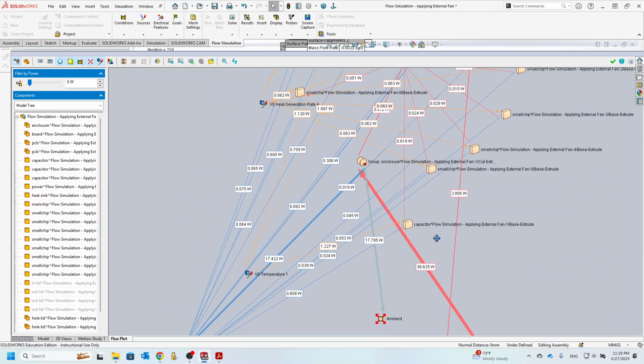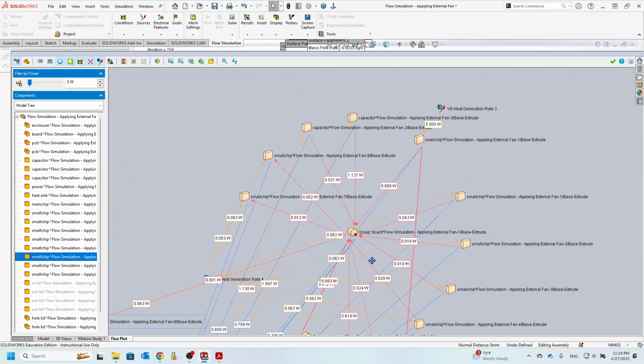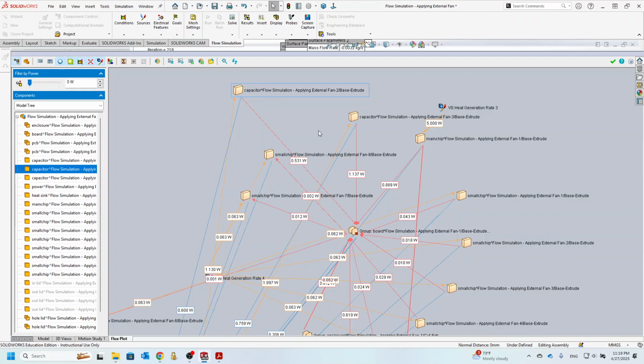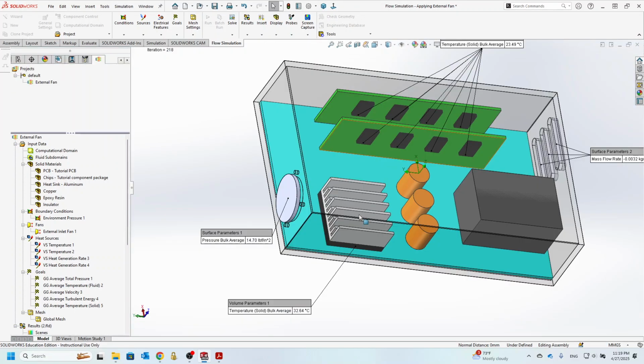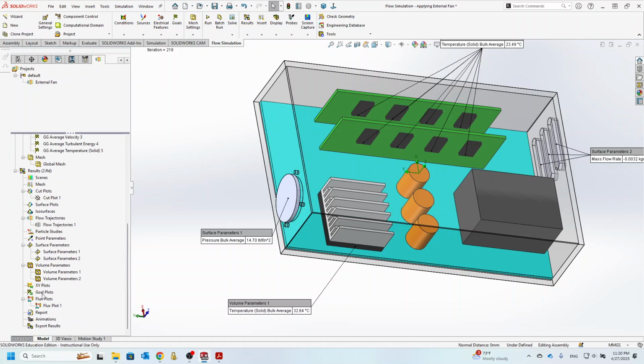So this is going to show us how much each component contributes. You can relocate it to show that, or you can, for example, remove a lot of these, like a capacitor. If you don't want some parts, you can easily create a much simpler flux block. That gives us a big overview of how much heat is exchanged between different components in this flux block.